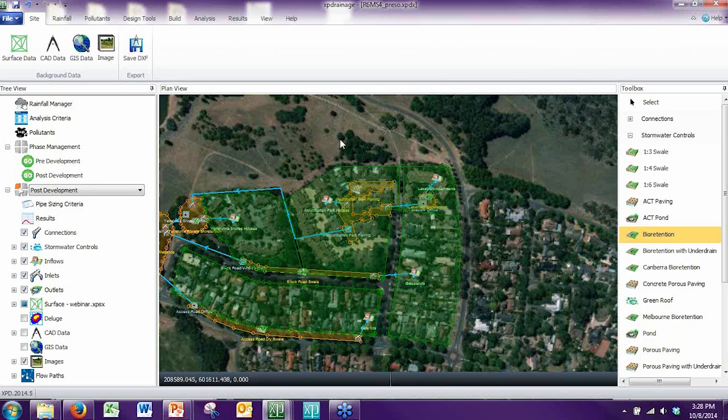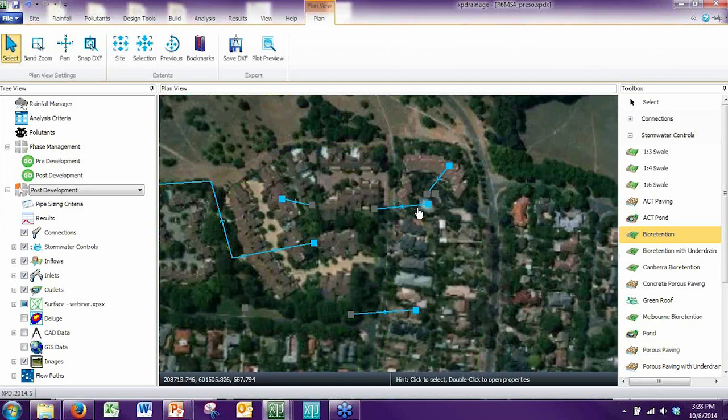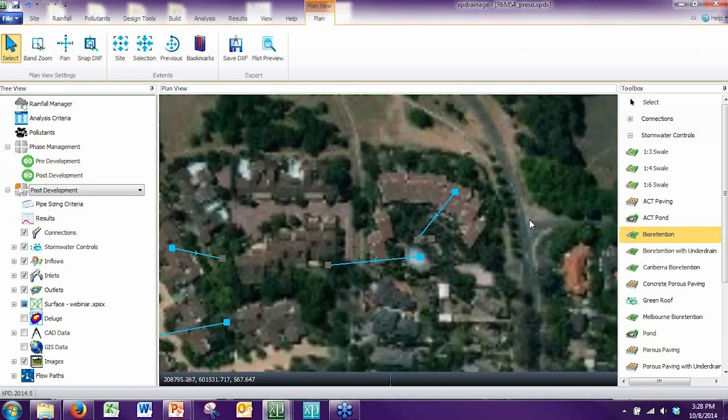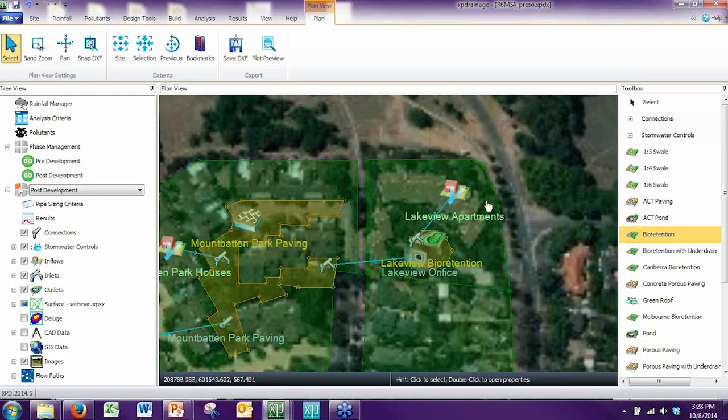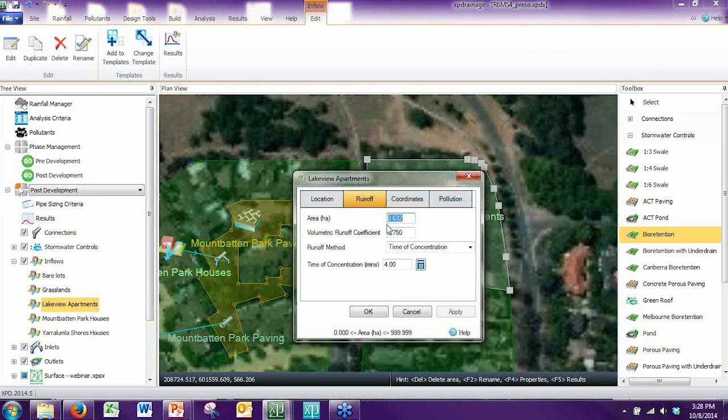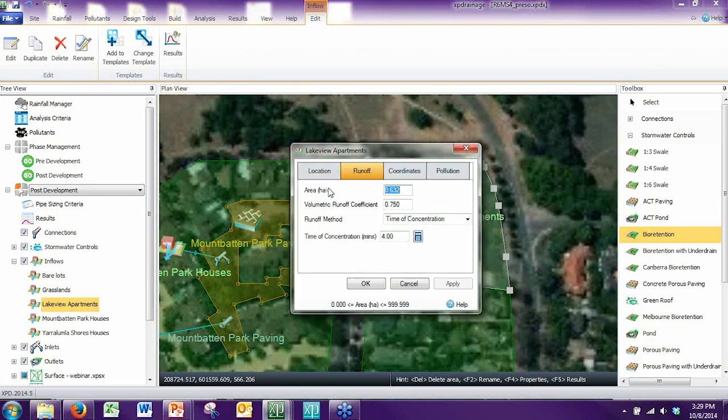So for example, we begin by putting in the drainage areas, and so each drainage area, wait just a moment for screen to refresh, so each drainage area can be brought in from CAD and is actually the actual area. Now you can overwrite that area or you can leave it, and so it's consistent with the areas in the other CAD files or GIS files.